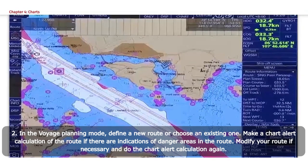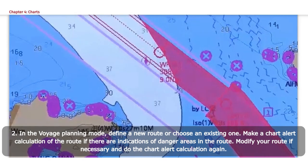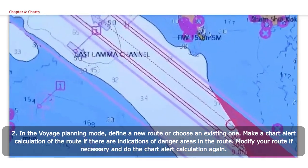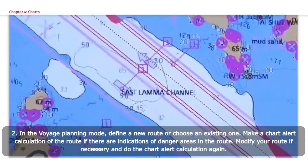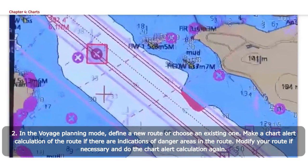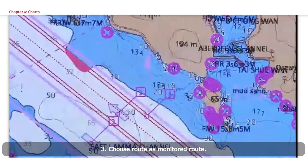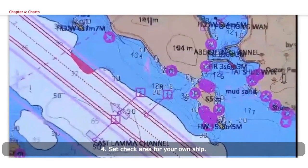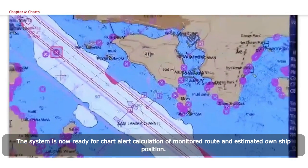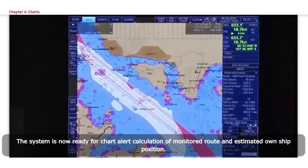2. In the voyage planning mode, define a new route or choose an existing one. Make a chart alert calculation of the route if there are indications of danger areas in the route. Modify your route if necessary and do the chart alert calculation again. 3. Choose route as monitored route. 4. Set check area for your own ship. The system is now ready for chart alert calculation of monitored route and estimated own ship position.